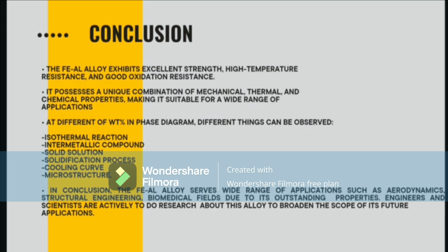The excellent corrosion resistance may also enable higher operation temperatures, thereby further reducing energy consumption. For large industrial facilities, support structures could be much leaner. For example, for a steam cracker, FeAl tubes would be employed.